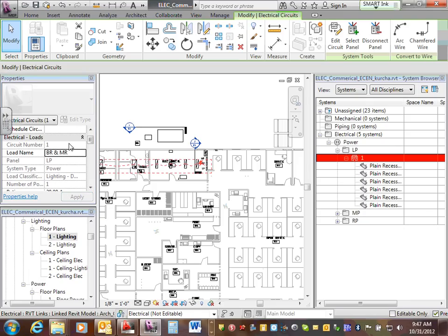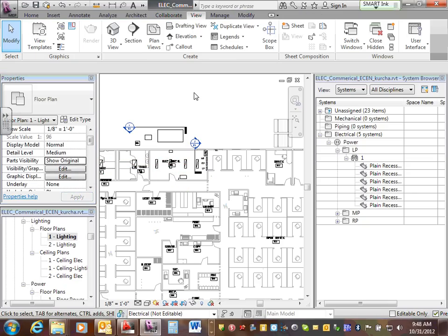So that will be your, and later on, guys, bathroom, you have to put the numbers here. Let's just do the numbers. What was the number here? Thank you. Bathroom 113 and 114, or both of them. Let's just say bath R 113 and 114, and mechanical room. What was the mechanical room? 117, 116. Thank you. So that's the name of the circuit. Apply. If you guys didn't do this, later on when you do the schedule, this will show the name of the circuit in your schedule.